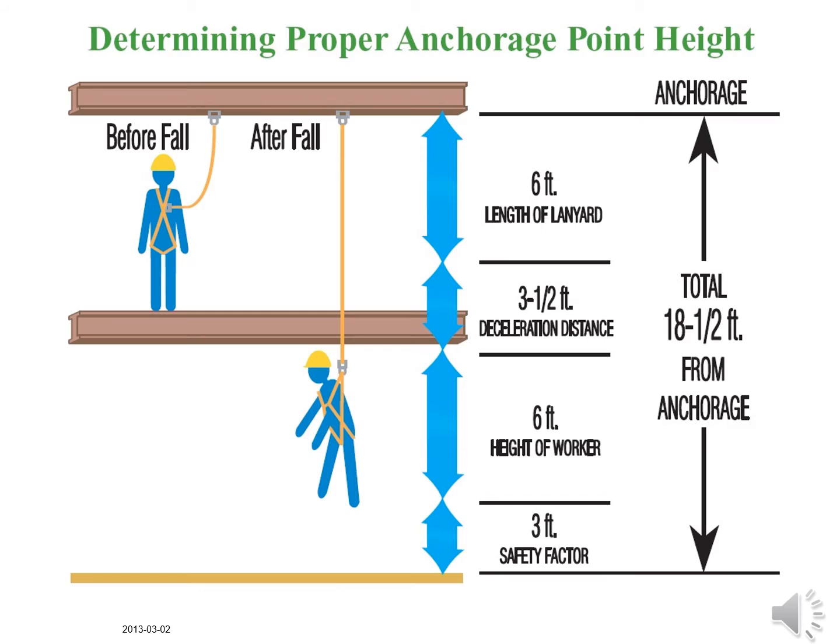When choosing that tie-off location, consider what's below. If there is energized equipment, moving machinery such as exposed drive shafts, or other potentially hazardous objects, calculating the correct fall distance will ensure that the worker does not come into contact with them.